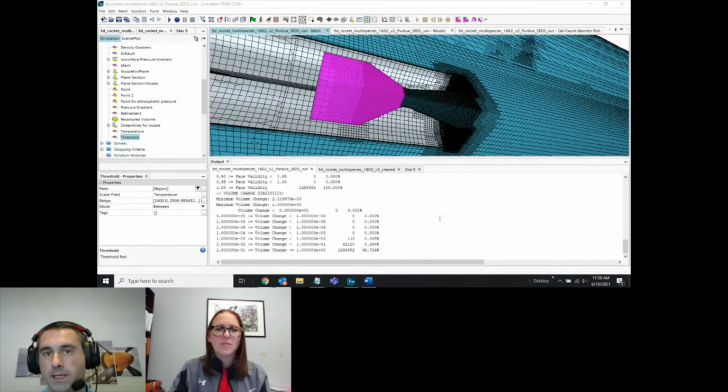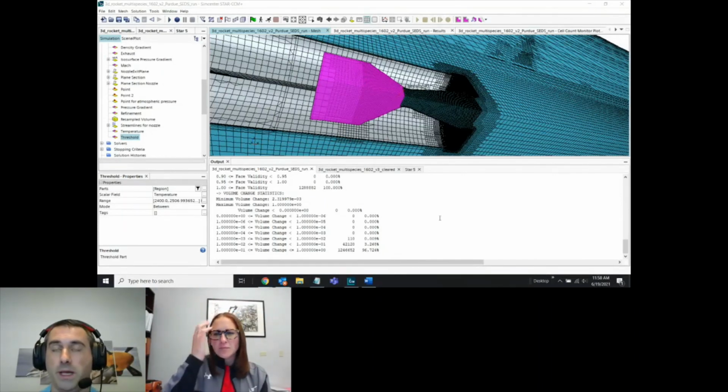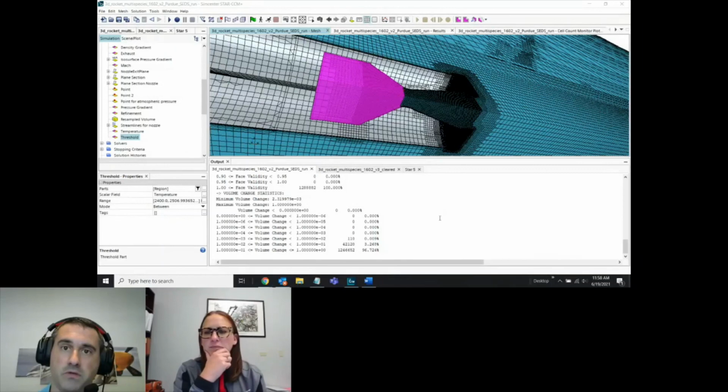You can technically export. You can do an export of XYZ position and pressure and shear forces, and then you can map that into a FEA package. There's a file export to import into FEA to do something like that. There are also other tools that we directly interface with that you can do a one-to-one match. For something like this, you're not going to need a direct coupling so much. It's more of just a one-time export and import to figure out what kind of load you're seeing.